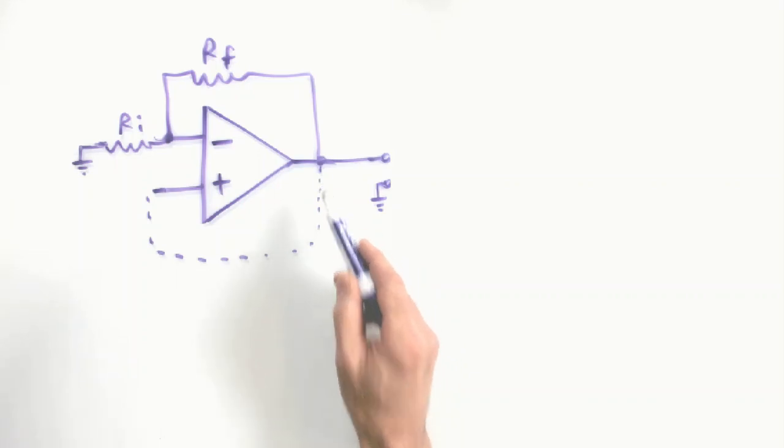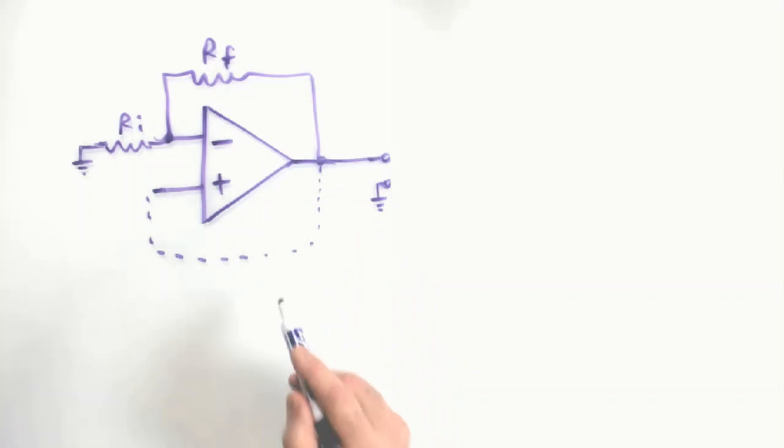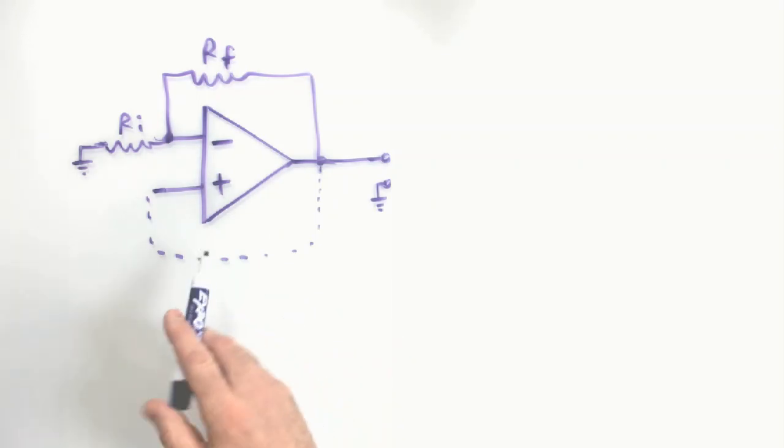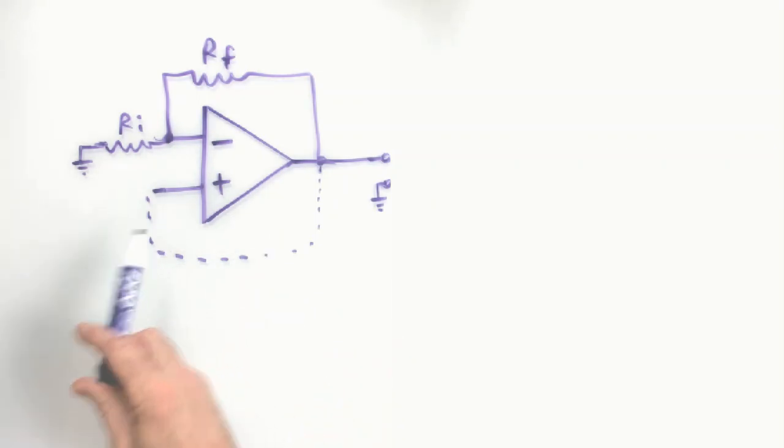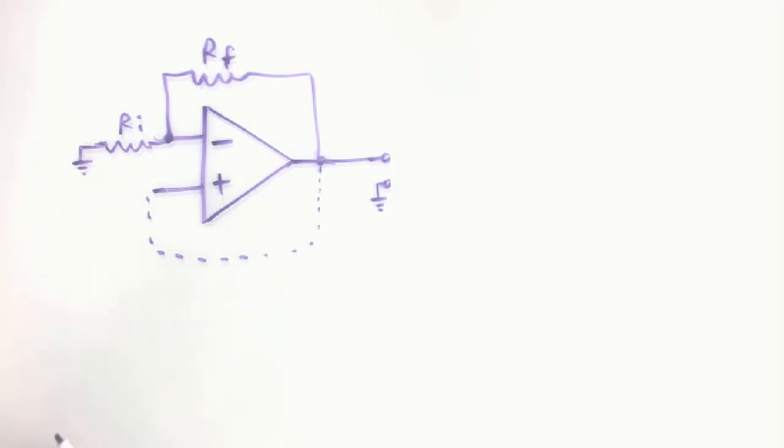Any type of positive feedback, and by positive feedback we mean that it's in phase, it's reinforcing, it's not going to cancel, it's going to reinforce and be a positive addition. So that's what causes the oscillation. So what the answer is, we use negative feedback to get an amplifier, and what happens if you add positive feedback to an amplifier? You get feedback, which creates a sustained oscillation, and that for us is going to be a feedback oscillator.